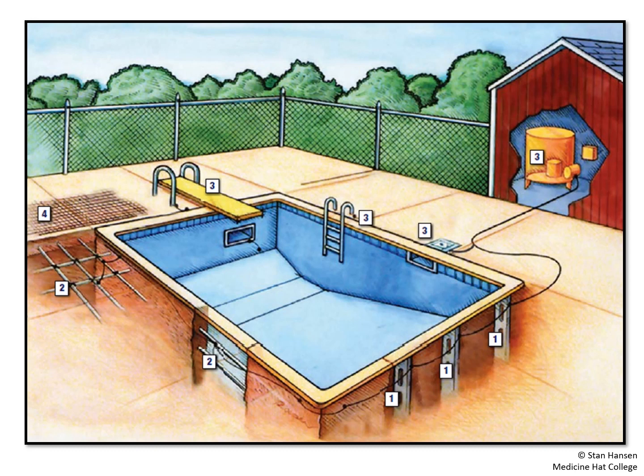All the bonding conductors must terminate at the panel board that is supplying the pool electrical equipment. If we have a dedicated panel just for a pool area, then we must run all of our bonding conductors back to that panel board. If we're using a panel board inside another section of the building, then once again, that is the panel board we must run all of our bonding back to.